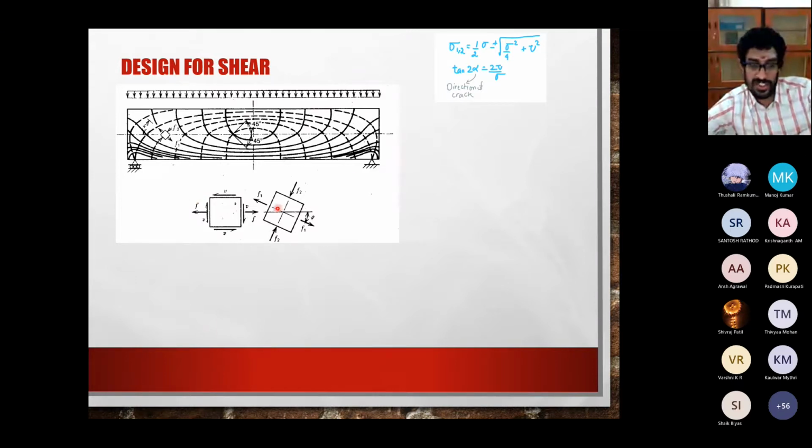The use of a Mohr circle is that if anybody gives you a set of normal and shear stresses, you would be able to find normal and shear stresses at any other inclination, which includes your principal stresses.